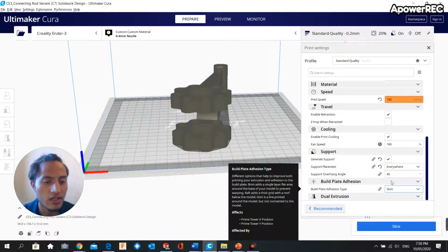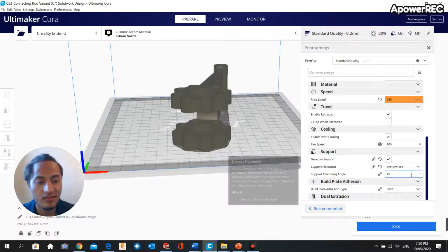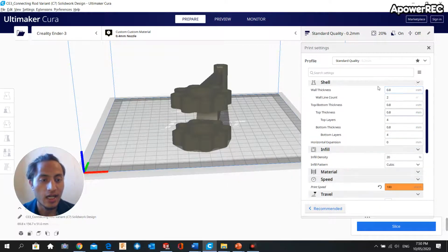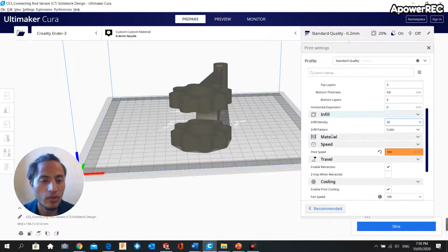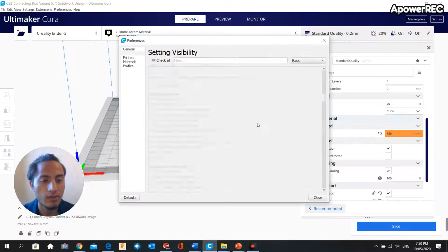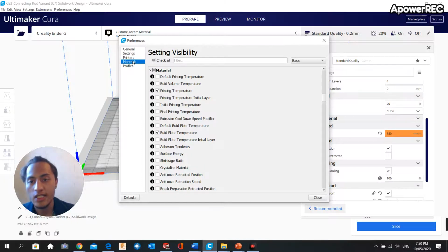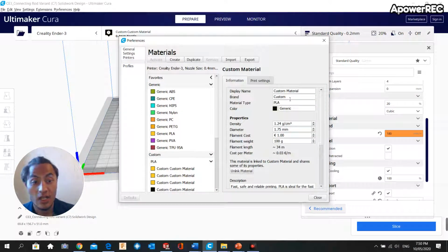And the skirt is obviously the addition best, make sure you also tick on that. So once that's done, also you have the material, what materials we used. So for material, go to material tab. We're using custom material, PLA generic, so it's a black color, so that's why it's generic. Make sure it's a black color, so obviously you can see density and diameter information here.